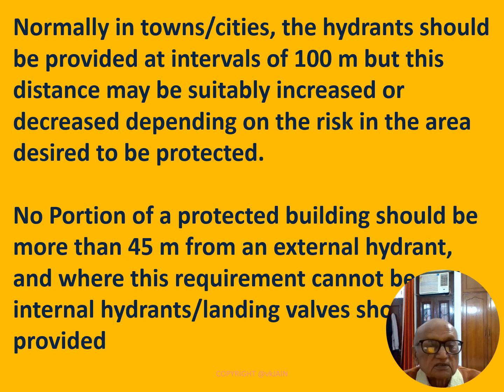I am talking of the town planning aspect. No portion of the protected building should be more than 45 meters from an external hydrant, and where this requirement cannot be met, then suitable distances may be adopted.